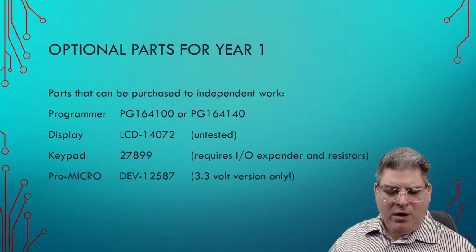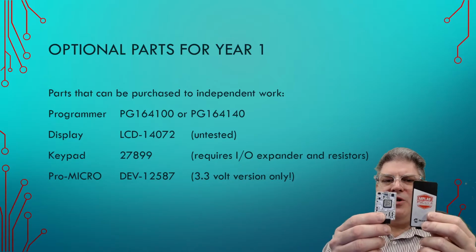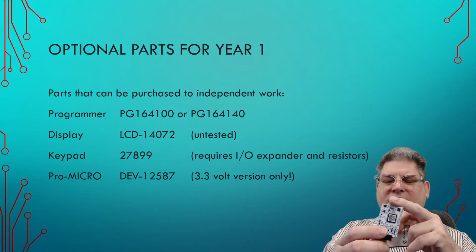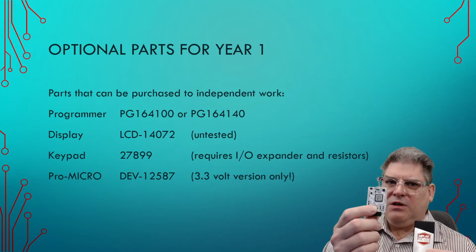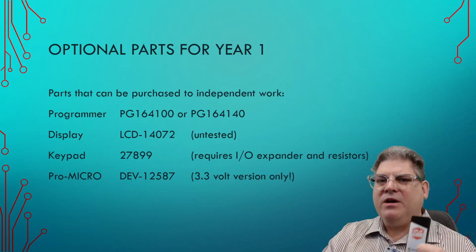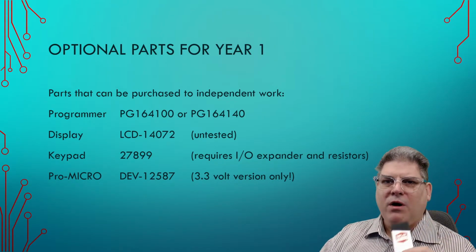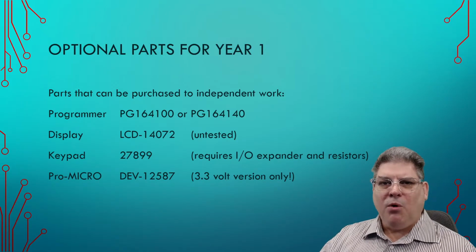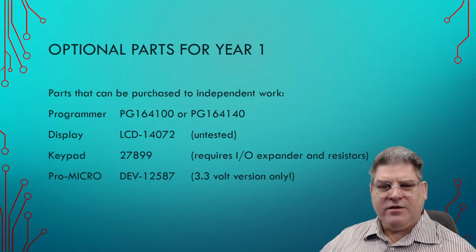One of them is a programmer, and we have a couple of variants of it. We have the PICkit 4 and the in circuit serial programmer called a Snap. Now, there are differences. This one's quite inexpensive, and this one is reasonably expensive. This is about double the price. But what this allows you to do is not just program your boards, but it will allow you to debug them and power them, and a lot of very powerful features as a full programmer.